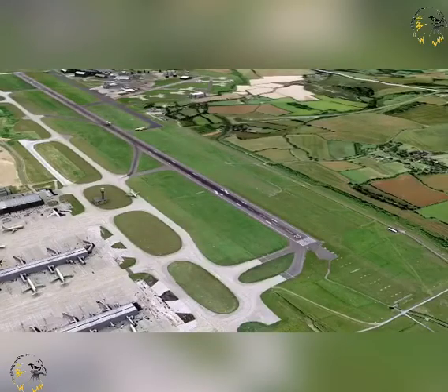The length of a runway should be adequate to meet the operational requirements of the aircraft that are intending to use the aerodrome. It should not be less than the longest length calculated to correct for local conditions of elevation, temperature, slope, humidity and surface characteristics. There is no requirement to cater for the worst-case critical aeroplane at maximum mass.